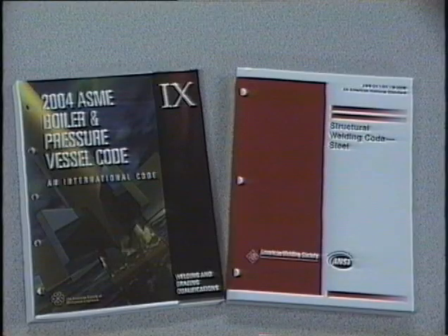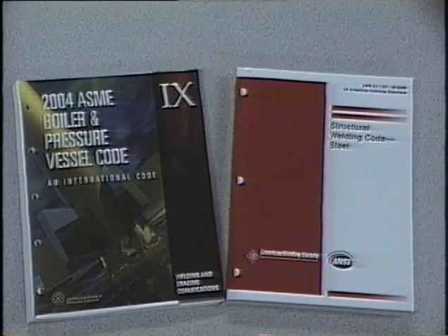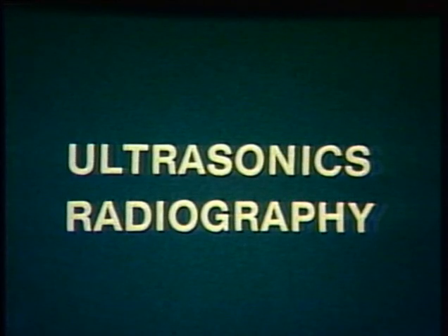Since many factors must be taken into consideration to make precise judgments, careful evaluation by a well-trained inspector is important. The inspector's judgments should be based on requirements specified by applicable procedures, specifications, or codes. Depending on requirements, a questionable indication may require further non-destructive testing, such as ultrasonics or radiography.